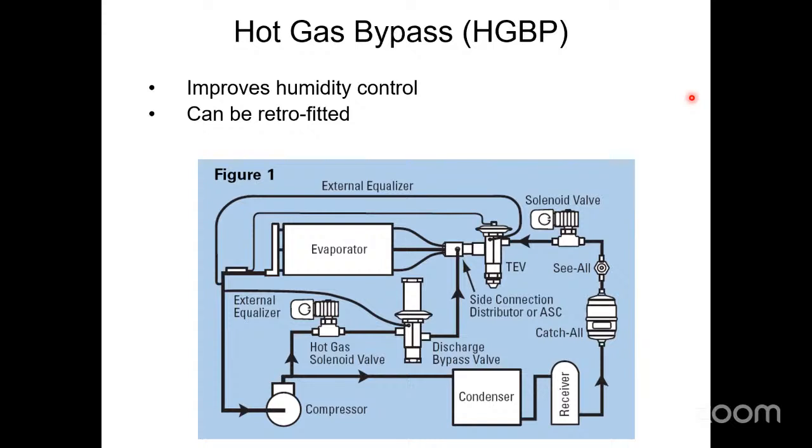in small pieces. So the way hot gas bypass works, if you don't already know, hopefully you're familiar with the refrigeration cycle, and I can skip that. But I got my evaporator, my condenser, my expansion device, and my compressor, my 4 major components on any refrigeration system. Normally, the hot gas leaves the compressor and goes over to the condenser coil where it can reject its heat to the outdoors, right? You're familiar with that. What hot gas bypass does is it bypasses some portion of the refrigerant around that condenser and takes it off the compressor and sends it directly back into the evaporator.